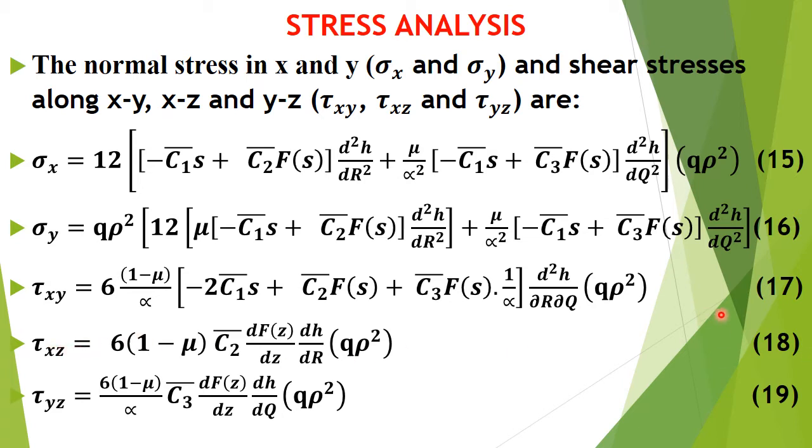So when we got all these equations, we now discover that all these equations are closed form solutions, because in our deflection equation we did not assume the displacement function as a polynomial. Rather we derived it from the governing equation, and then we got the exact displacement function, the exact displacement polynomial function.